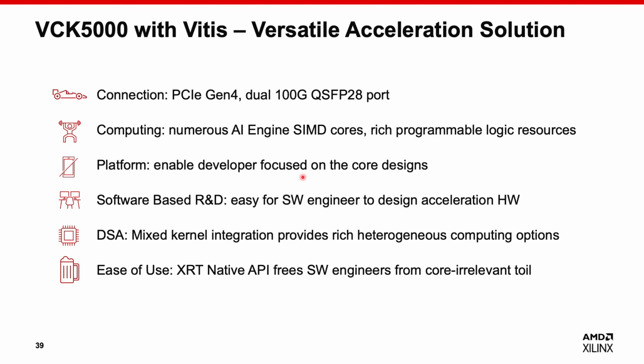The target platform handles all the housekeeping jobs and lets the developer focus on the core designs. The software-based R&D flow makes it possible for software engineers to develop hardware acceleration applications. The supported different acceleration kernel types provide different acceleration options. And finally, the XRT native API makes it easy to program the host application.